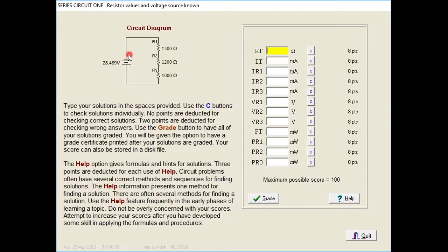So let's use the software and let's look at this and analyze it. So if we follow the negative electrons, there's only one path. So that's a series circuit or a series loop. It does not branch off and go through other components anywhere else. Think of it as a single lane highway for electrons. So we have current flowing from minus to plus, one single path, creating our series loop. And the one thing that we have to remember, Kirchhoff tells us the current is constant in a series loop.